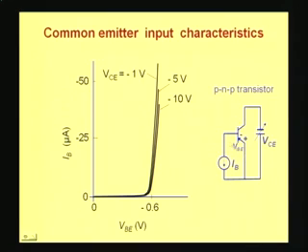So that is why there is a constant factor between the base current and the emitter current. So the emitter current is also approximately 100 times more than the base current, or told in another way, the base current is a fraction of the emitter current, which is almost constant when the biasing voltages and currents change.